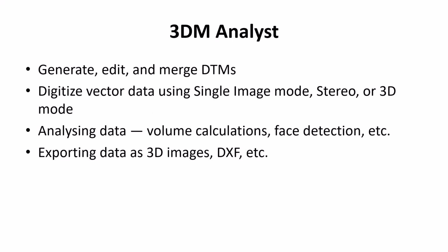3DM Analyst is the other main component of the suite of software from 3DM. It can generate, edit, and merge digital elevation or digital terrain models. It has digitization modes for digitizing linear features, planar features. We often do that in the stereo mode, and if you have a 3D monitor and 3D glasses, you can do it in a fully immersive 3D mode. We also use Analyst to analyze the data, do things like volume calculations, map or do automatic detection of planar faces. And the end products can be exported out of 3DM Analyst as 3D images or DXF files and ASCII files.